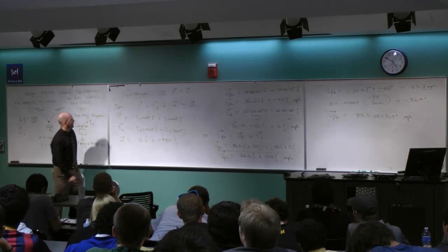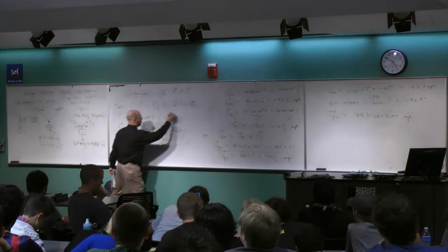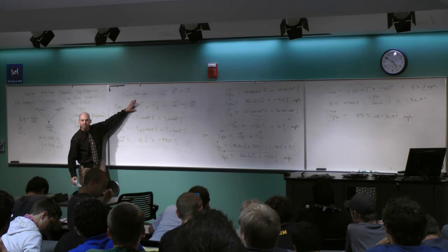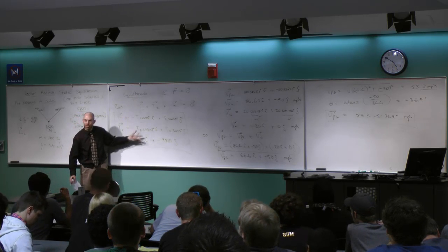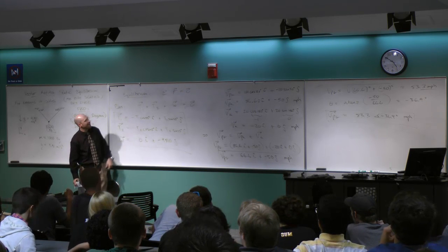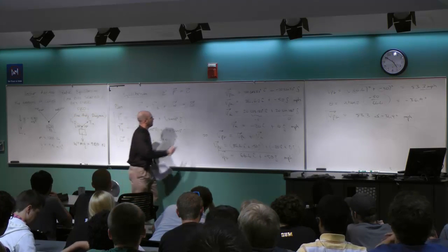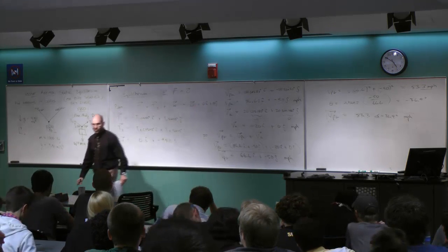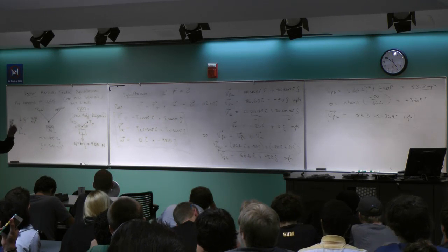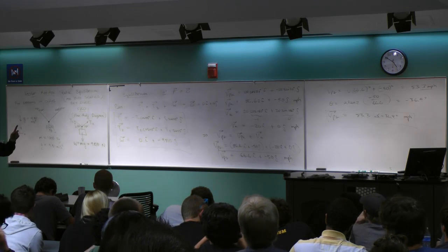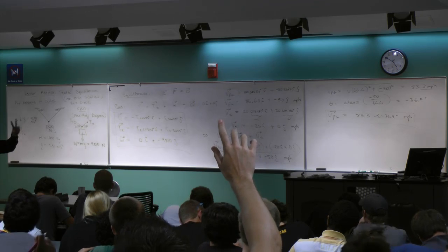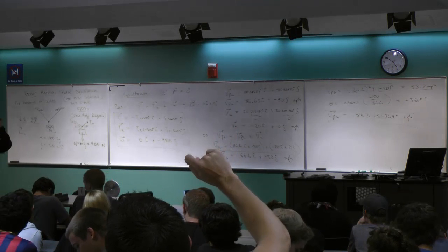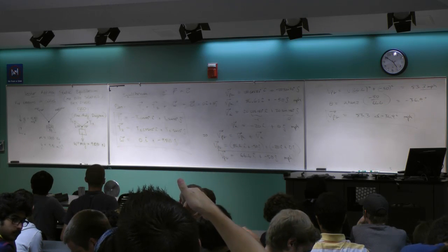So here's the thing. When I take these three vectors, which is half the problem, write these down, and substitute them in, I'll have two unknowns, T1 and T2. And I will have to add them up to get 0i plus 0j. So when I set the i's equal to 0, that'll give me one equation. And when I set the j's equal to 0, that'll give me the other equation. And I can solve for my two unknowns. Okay? The details are in the notes, but if I were you, I'd go back and finish this because it's insightful.